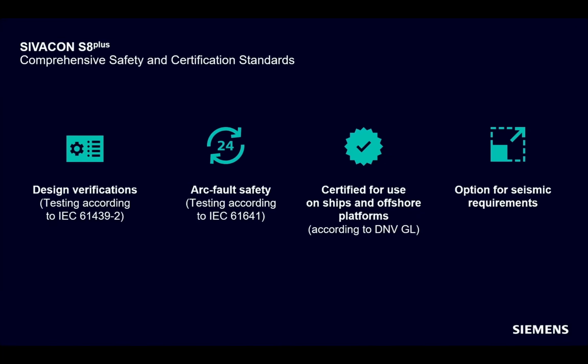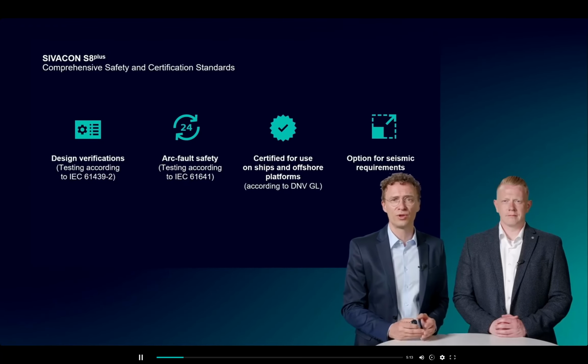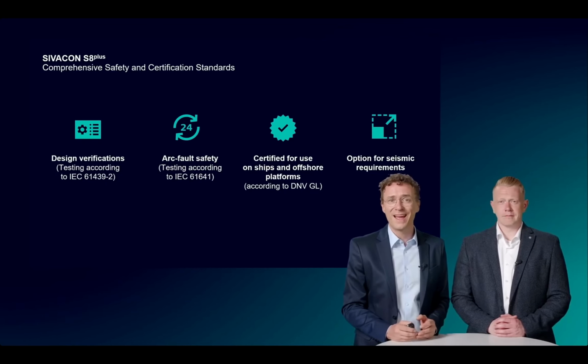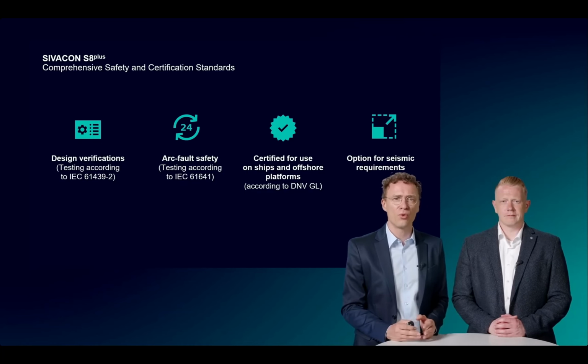That's how the switchboards are called in the standard. We have the protection relay for the left-hand feeder, the protection relay for the right-hand feeder. It has also been tested under arcing conditions in accordance with IEC Technical Report 61641. Additionally, it has been certified for use on ships and offshore platforms according to DNV GL and has an option for seismic requirements.